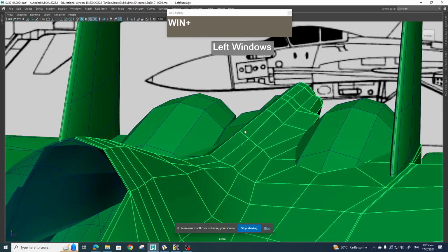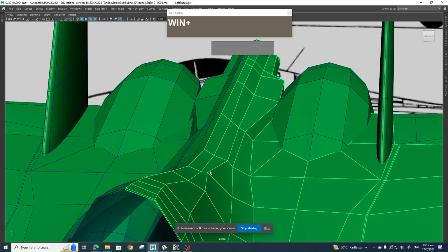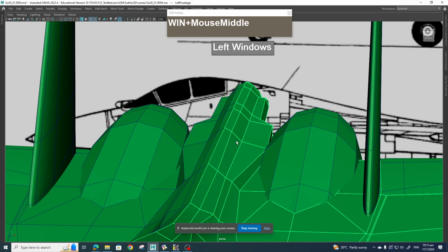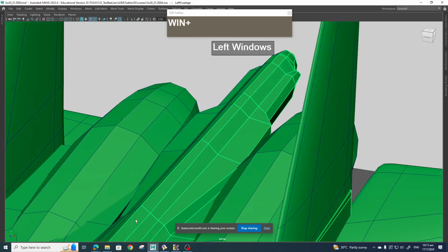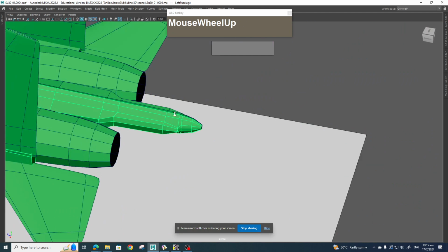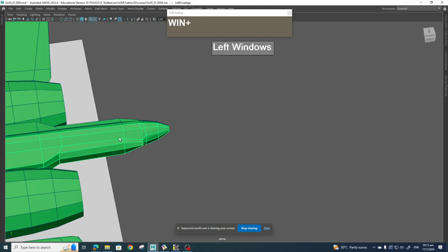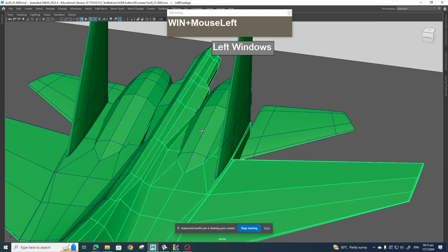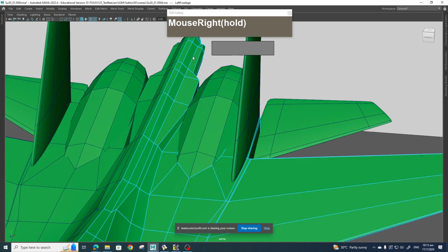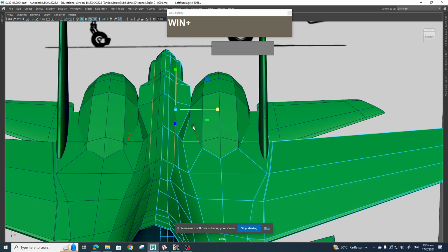and I'll try to straighten this area here, and then possibly add another edge loop right about here to support that loop. Before I insert the edge loop, let me just fix the straightness of this edge first. So I'm going to select this edge loop all the way to here, holding down shift, double click, then using the scaling tool, I can straighten this edge loop, and then use the move tool and push it back so that we have a tighter cross section right about here.